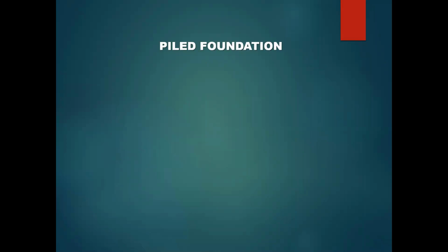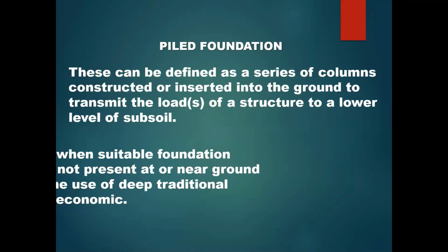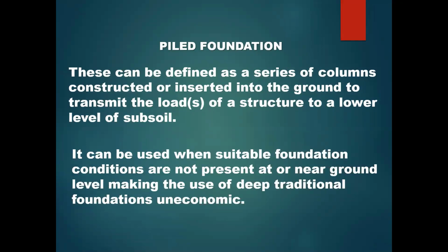And what is pile foundation? This can be defined as a series of columns constructed or inserted into the ground to transmit the loads of a structure to a lower level of subsoil. So that is what we call the pile foundation. Now, it can be used when suitable foundation conditions are not present at or near ground level, making the use of deep traditional foundations uneconomic.